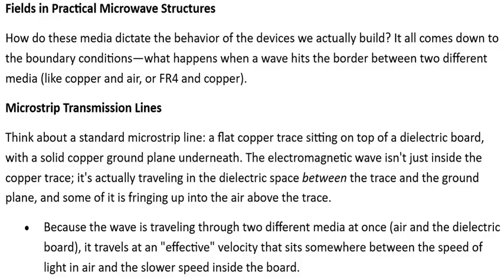Fields in practical microwave structures. How do these media dictate the behavior of the devices we actually build? It all comes down to the boundary conditions. What happens when a wave hits the border between two different media, like copper and air, or FR4 and copper? Microstrip transmission lines. Think about a standard microstrip line, a flat copper trace sitting on top of a dielectric board, with a solid copper ground plane underneath.